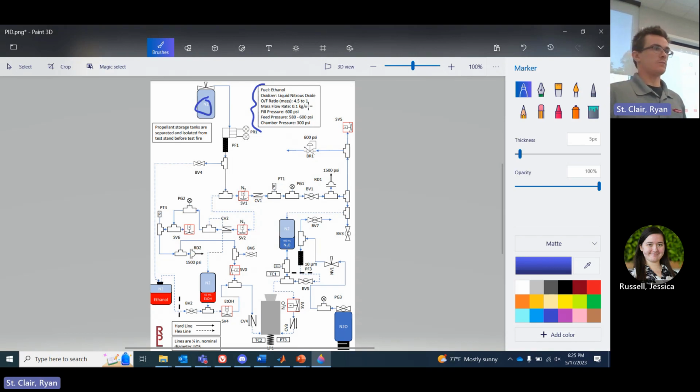The other thing is that exact ratio to get all of your oxidizer to combust with all of your fuel. That's called the stoichiometric ratio, and it produces the hottest flame and is the most reactive propellant combination, but it produces a lot of wear on your system. It can make it very hot and can cause your engine to melt. A lot of people designing these rocket engines are very concerned about reaching that stoichiometric ratio and make sure they're just below that, or only as high as they need on this OF ratio.